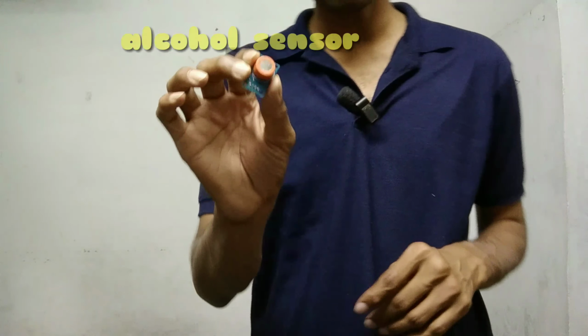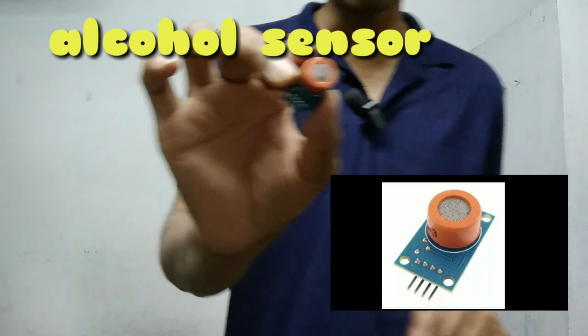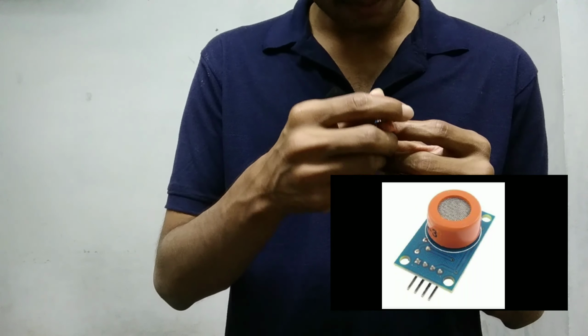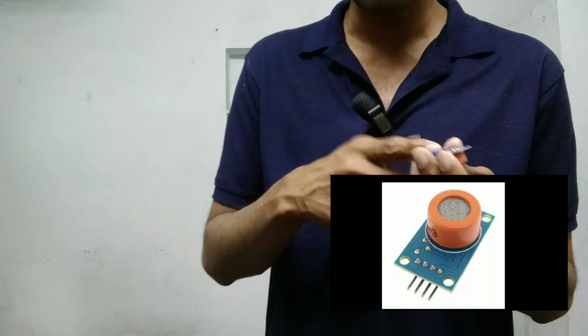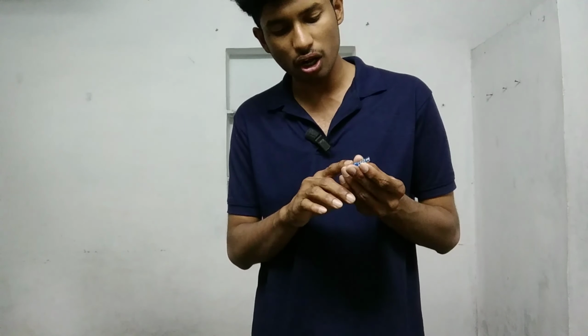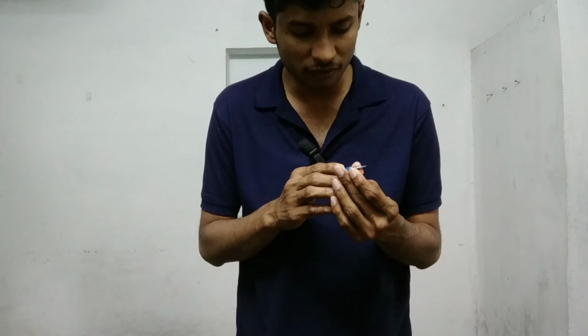And coming to the next sensor, this is an alcohol sensor. Like the smoke sensor, it has 4 pins: A0, D0, ground, and VCC. If you want to connect it for analog readings, you will connect it to A0 to A5, and if you want to use the digital output, it will be connected to one of the pins from 0 to 13.